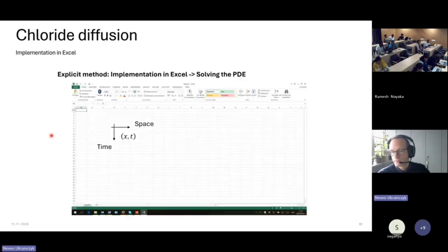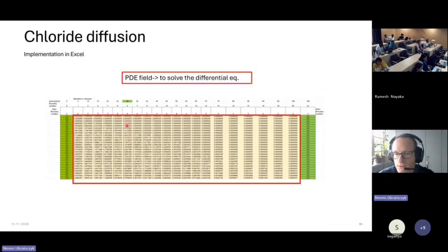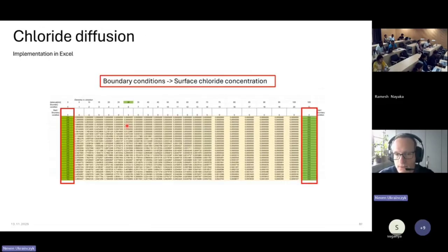Okay, now I will not explain this. You can implement it in Excel, then you just follow this. So you can see here we have the boundary conditions, the 3%. This is the inner wall, so we will put just 0, or we can put an adiabatic boundary condition.